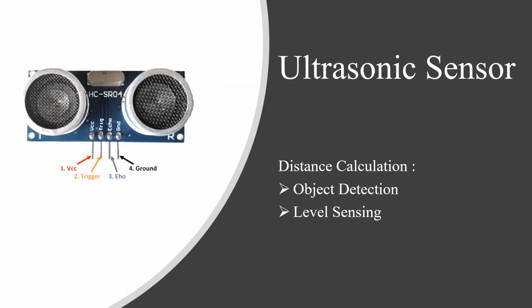Now when someone comes close to the dustbin, it detects the object, and when it's closer than 1 meter, essentially meaning that someone wants to throw trash into the bin, it triggers a PWM signal, which essentially turns the servo motor, which I'll explain later, and opens the dustbin. Now another sensor is used for level sensing, and this is mounted inside the dustbin at the top corner, so that when the trash is full and something is detected, it triggers the LoRa module to send a signal to the PC terminal in order for the trash to be collected.